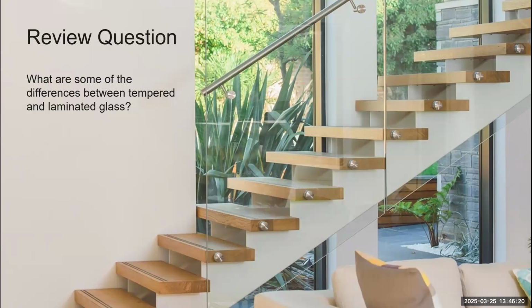Then we do have a wind velocity or pressure category. When we have a balcony that is covered, we only have to take into consideration the pressure from the outside. When we have a guardrail system that is on top of a parapet or uncovered, we have to take into consideration the positive and negative pressures in combination. So in essence, your system will get more robust, your anchors will get deeper, and you will have a lot of impacts by mounting it onto a parapet.